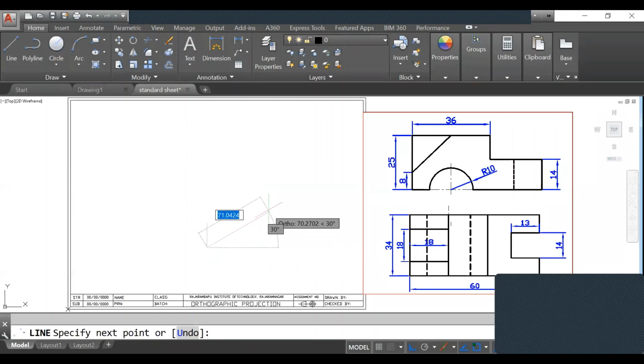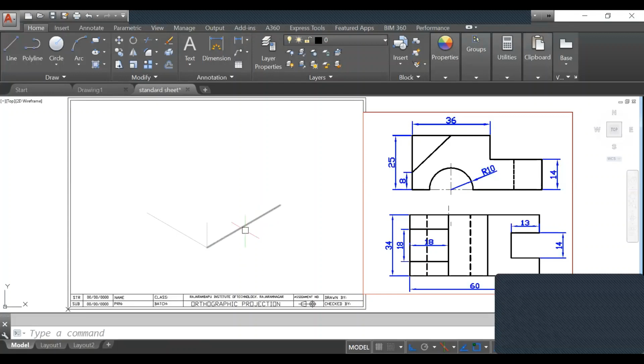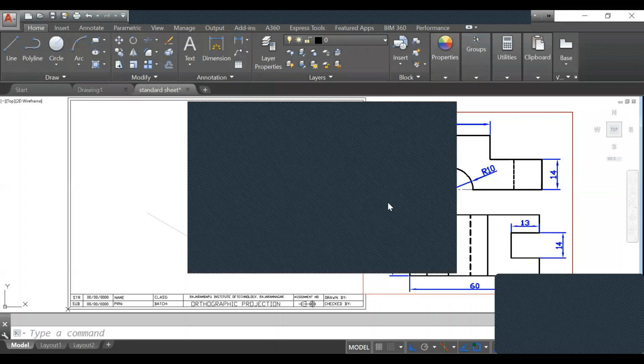Then from this point, you can see here, if I consider like this one and this one, F5. Okay, so where to draw the front view and where to draw the side view? That is the main question here. This O should be matched with this one. If I capture this one and place it here, then this O, this point and this point are overlapped. But if I capture this one and place it here, this front view on this side, this O would be on this side. That is wrong. So the front view should be on this side.